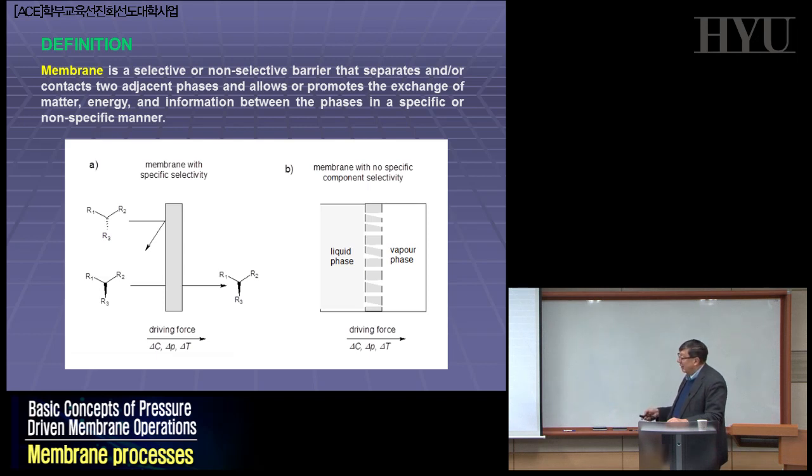To realize through this interface what normally is realized in a distillation tower, where you have condensation, evaporation, condensation between different places, you can compact all this in a system which is your membranes. Membrane distillation is exactly this. In this case, no selectivity, but what you have to realize is a very interesting thin layer that can facilitate these contacts between the different phases much better than the other traditional way of doing until now.